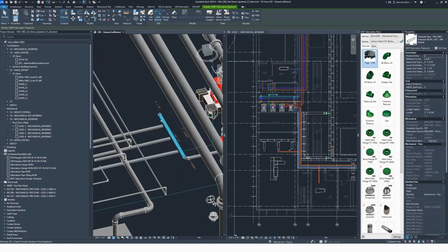One of those hidden functionalities is that they'll actually maintain those slopes for you. So you start routing around, you can always leverage those elbows right up until you go up or down. Because another fun fact, an elbow up or down will always be perfectly vertical. Never pulling in any of those weird angles, never giving yourself a riser that moves a foot over by the time you're at the roof. Nice and easy to get these things laid out, perfect verticals every time.